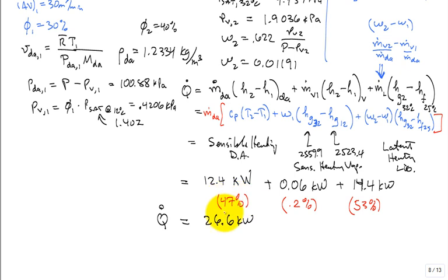And believe me, out there in practice, this is one of those things that if you're ever in the MEP field, you're ever doing air conditioning in South Texas and all that, they want to bust it out, and the people want to double check that you've accounted for both the sensible load on that coil as well as the latent load. You wouldn't believe how many times I get asked questions like that. Okay? Can you double check these calculations? Somebody's insinuating I forgot the latent load, or claiming I didn't account for it in my design. Okay? So that's what they mean. There's a lot of energy that has to be supplied or removed to a coil. Supplied to a heating coil if you're having to vaporize, removed from using the coil if you're condensing.